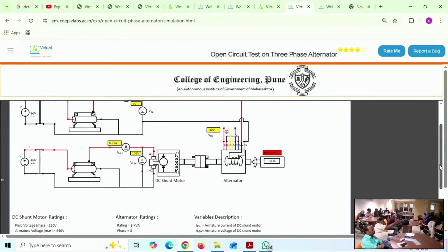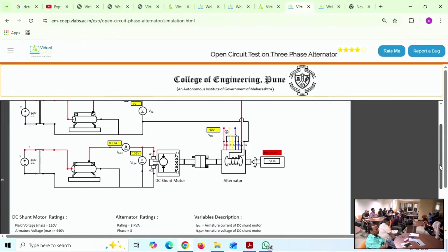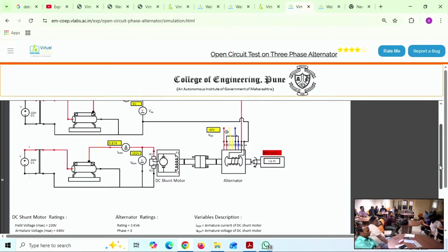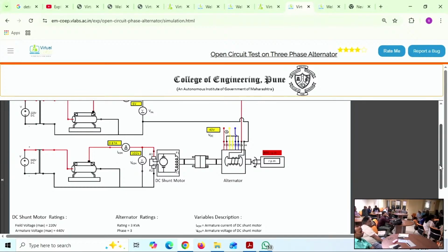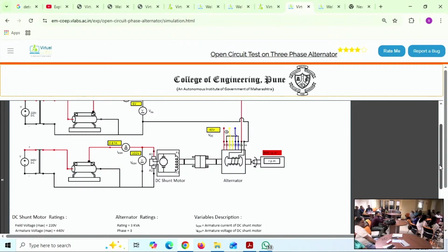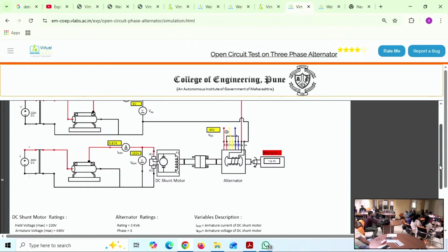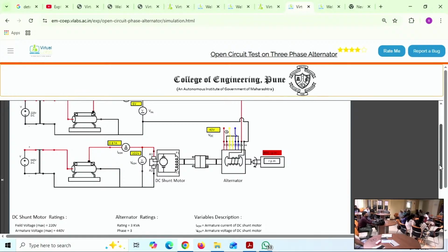Usually, yes, your idea is correct, sir. We can have that flux resistance control method also, provided the flux gives the maximum. EB is equal to Z pi P n by 60A. If you take the generated voltage, flux and speed relation, speed is directly proportional to EB and inversely proportional to flux in a DC machine. So I am saying, increase the flux, decrease the speed.